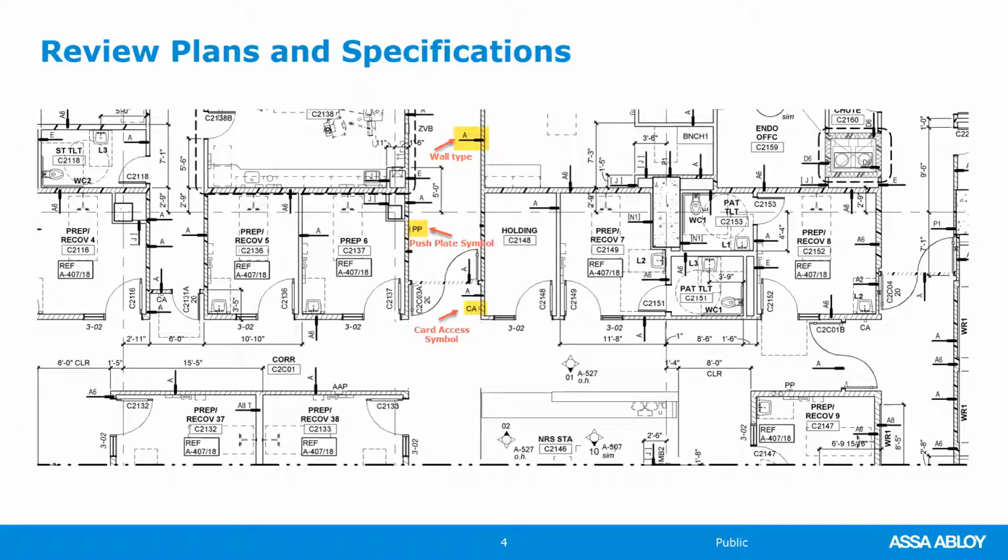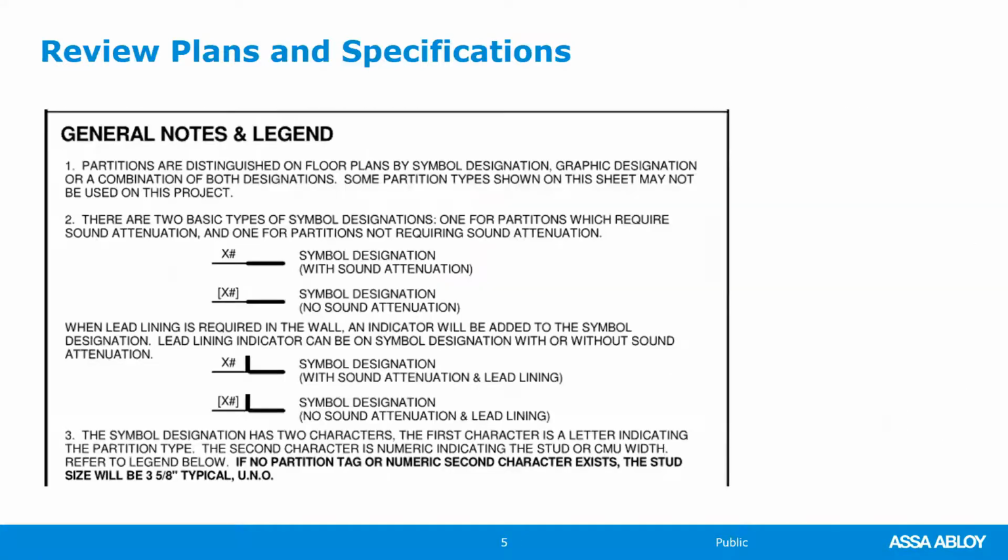And then continuity. I like to color my plans, even when I'm doing a takeoff, to just make sure that all of the doors within that fire rated partition are in fact listed as fire rated on the door schedule and vice versa. And if I'm selecting hardware, if I'm writing a specification, a lot of times when you get the door schedule, the fire ratings haven't been put on there yet, and it's always good to cross-check it with the floor plan.